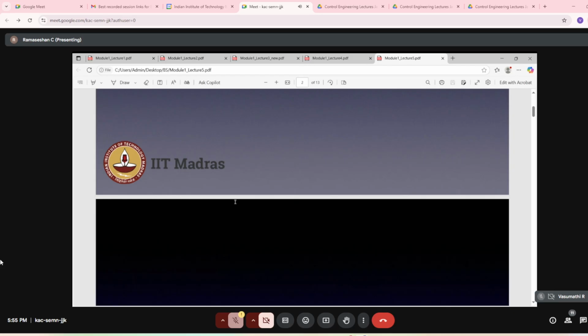This is just for the sake of exhaustion. We will not be dealing with non-causal systems in our course. Non-causal systems do happen only when a signal is not a physically meaningful signal. So it's for systems that are not physical, but you hook up in your computer. I can always write a computer algorithm where q of t is some function of q of t plus 1, correct? So I can always run the system from future to the past rather than from the past to the future.